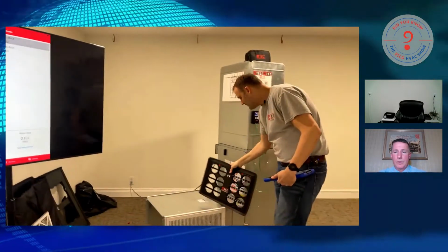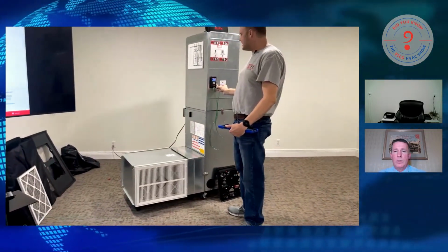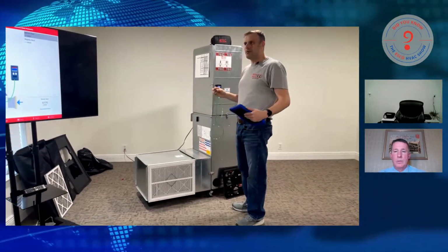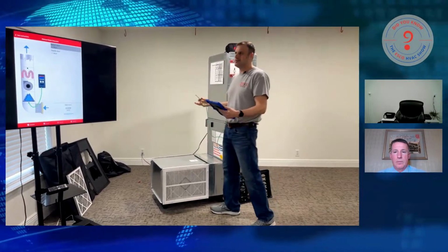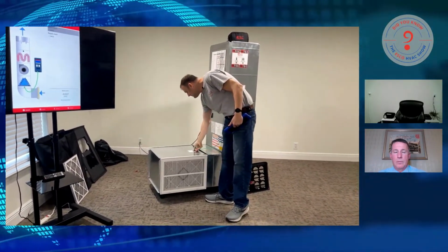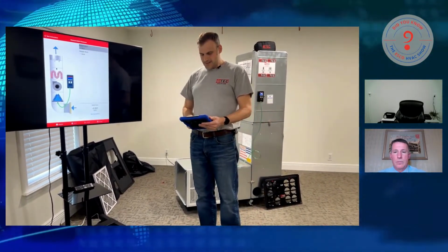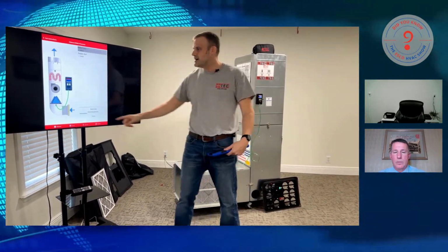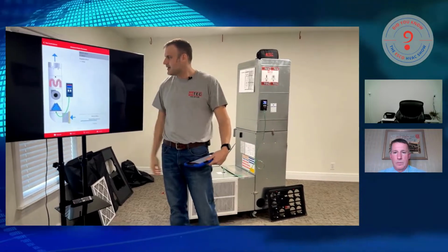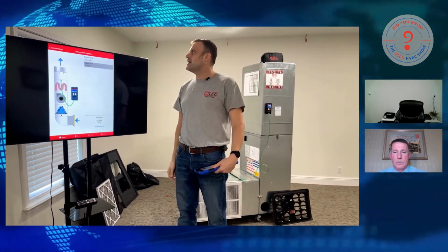So I'm going to set our Trueflow out of the way for a second. Right now, we're just using the DG8, and we're just static pressure mapping the system. That's what this is called. We're pressure mapping the system. So we're going to go into the return, right? And we're going to take that measurement. So our return ductwork, filter and return ductwork, is 0.356 inches of water column.